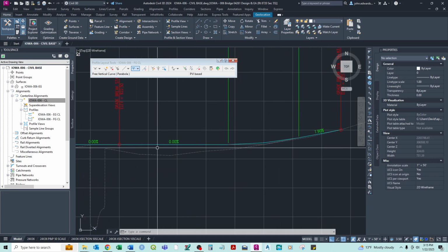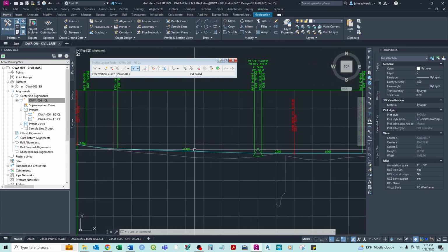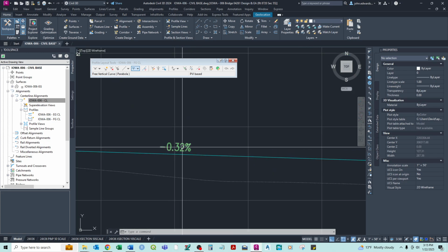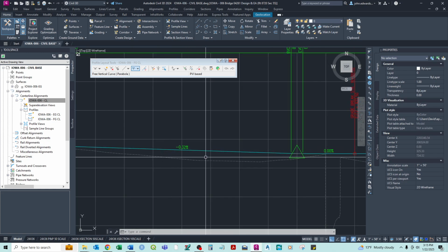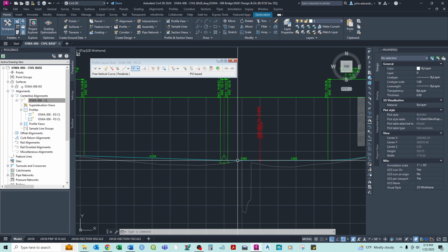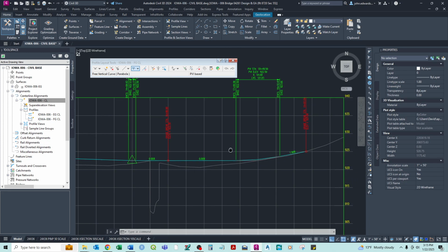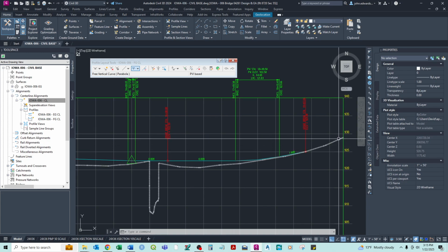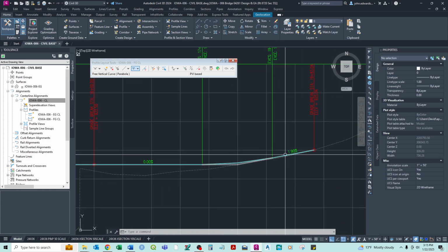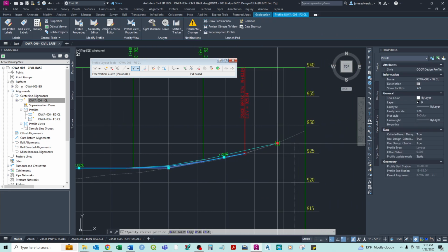And another consideration, obviously within this design, is general drainage. We have a very low slope of only 0.32 here. Normally we want it to be at least 0.5%, if not 1%, sloping down here. And again, we have this long stretch that's just 0%. So it would probably be better to come further back up in here. We could potentially drag this further back.